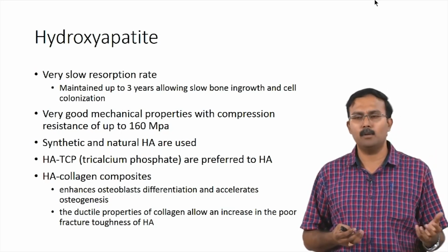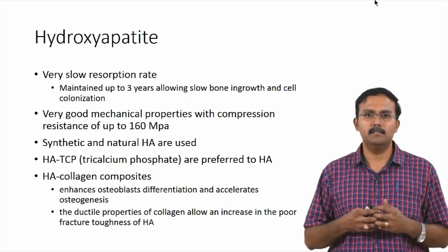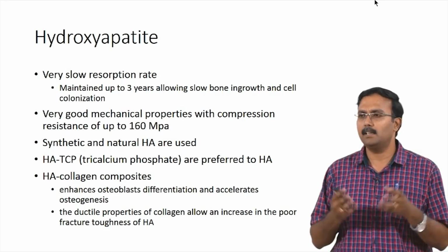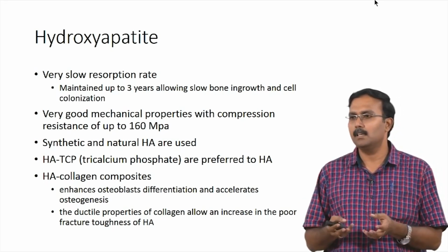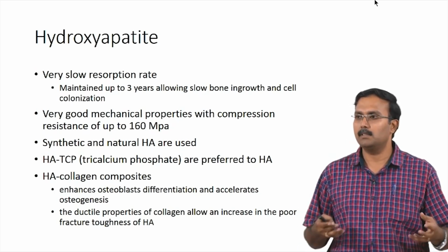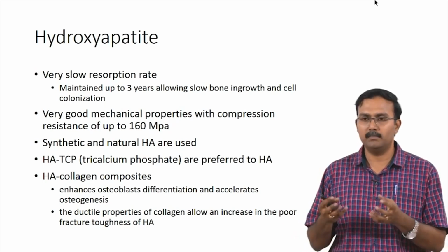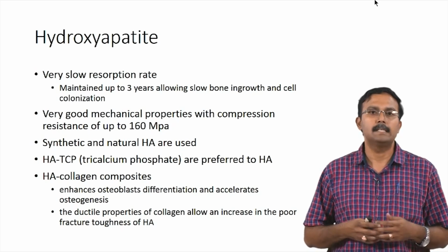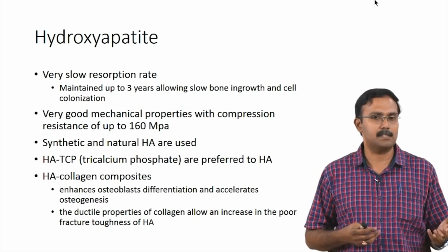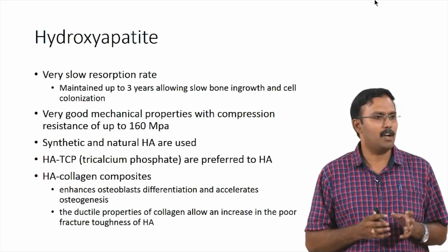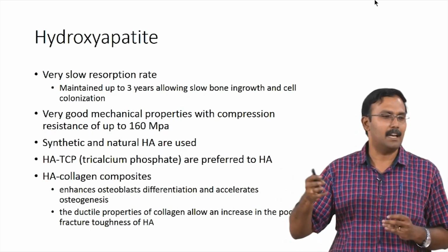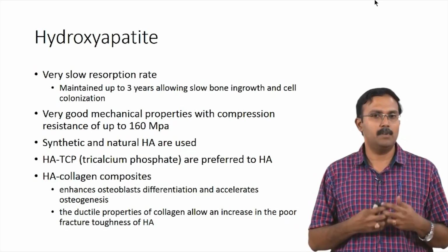They can be maintained in your body for up to 3 years, and this allows slow bone ingrowth and cell colonization. It makes sure that your implant is going to be there, and because it is hydroxyapatite, which is present in your body, it is going to integrate very nicely. It is going to bind with the bone and become a part of the new bone itself. It has very good mechanical properties, with compression stresses close to 160 megapascals, which is good, but still not as good as your bone, right. Your bone compression stresses are usually in the 10 to 30 gigapascals range.